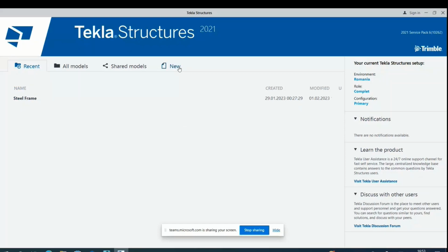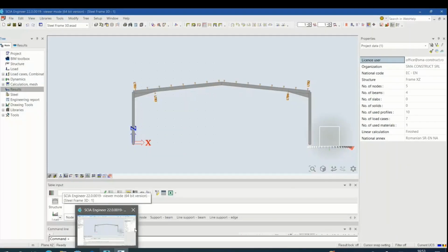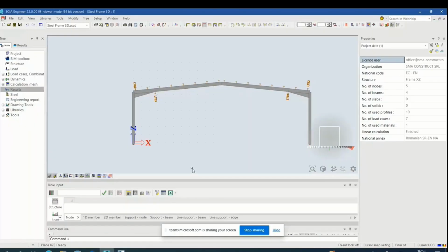When you design a portal frame, you have to be sure that the elements are capable to take the loads in section, and also by the elements you have to make the stability verification checkings and the resistance checkings in sections, also the frame.